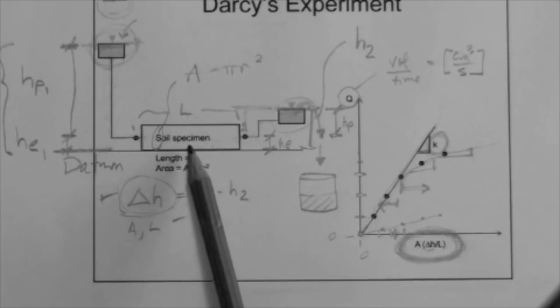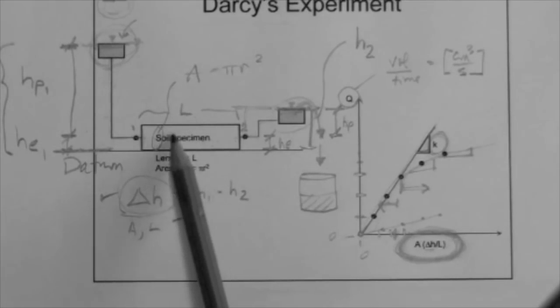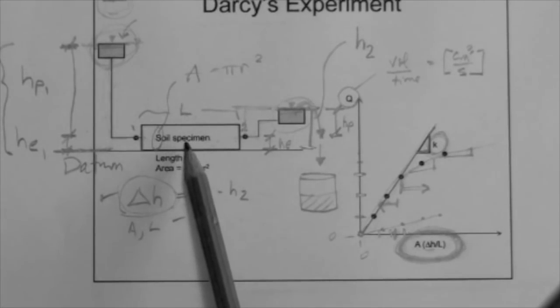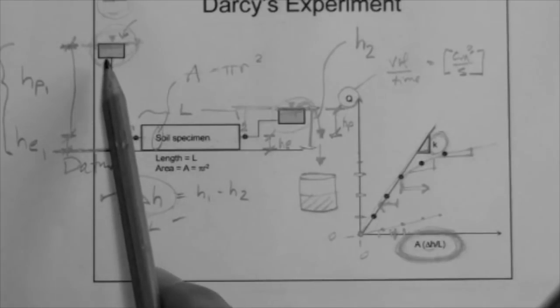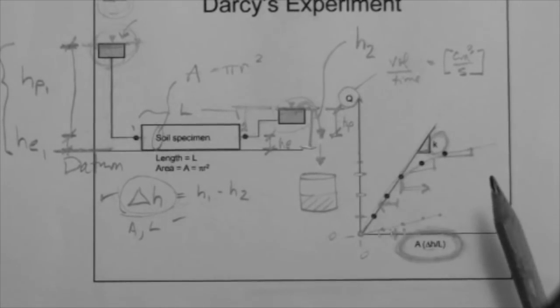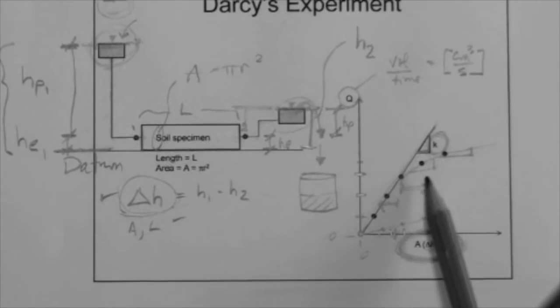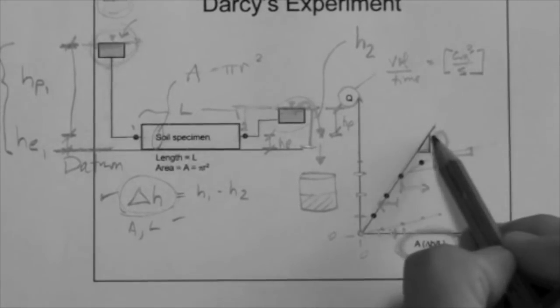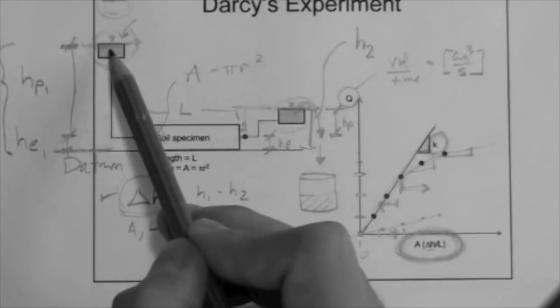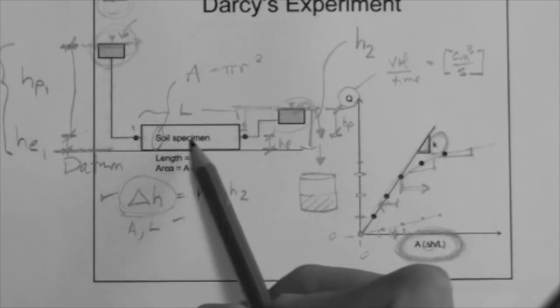If particles are moving around in there, then the soil as a unit, or as a fabric of particles, is being changed. That is, the fabric is being changed by the water flowing through the specimen. That can happen, but it renders the determination of K for that test null. Why? Because the K that you measure is the K for a given soil, not for a soil that has changed because the water has changed its fabric.